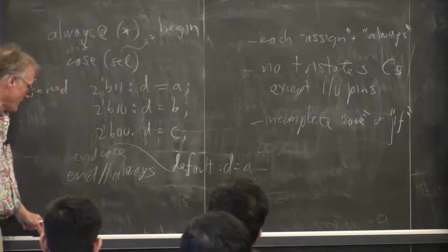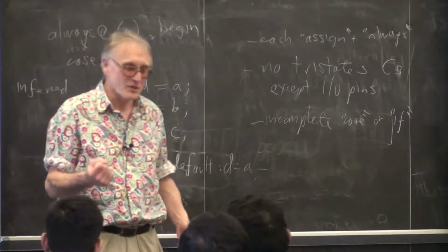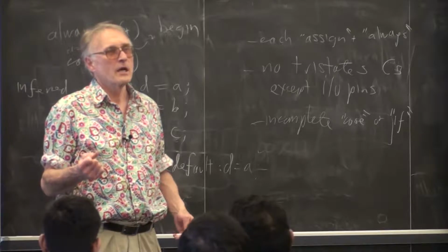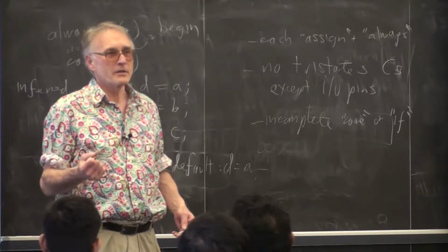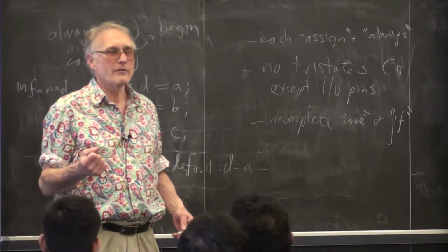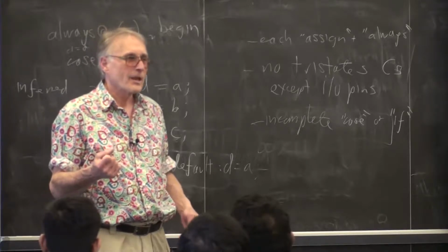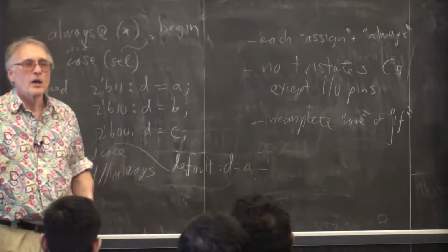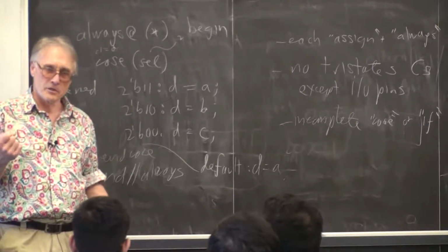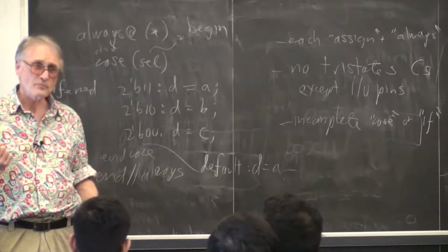And I did one the other day, which is a mistake I know I make. So I was pretty sure I made it when the results didn't work out. The effect was I was building an audio signal output, and I added one more filter and everything completely broke and the output was completely silent except for a little bit of crackling. And that was because I neglected to declare the output wire from the module as a multi-bit wire.